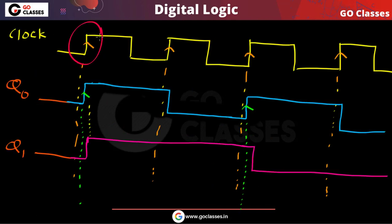Now you can notice here the clock is going from 0 to 1. So you are changing the input, but the output will change after some time. This is the propagation delay. Similarly, here Q0 is going from 0 to 1, so the output Q1 will change, but after some time, after the propagation delay.